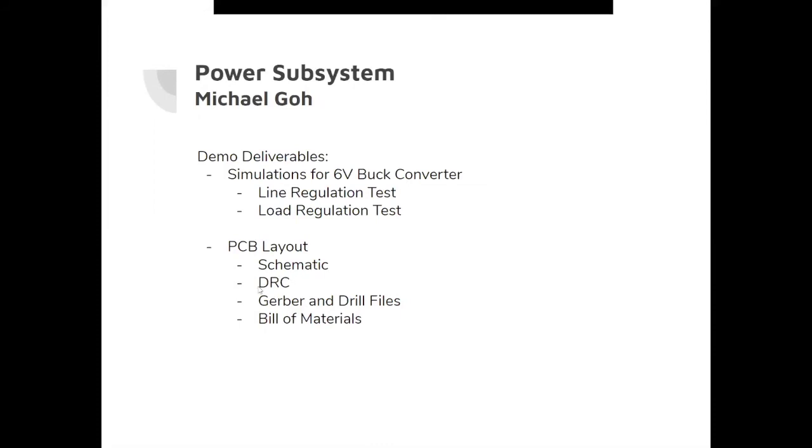I'll be going over the simulations for the converter, including the line and load regulation tests, and then showing my PCB layout, including the schematic, DRC tests, Gerber and drill files, and lastly, the bill of materials.